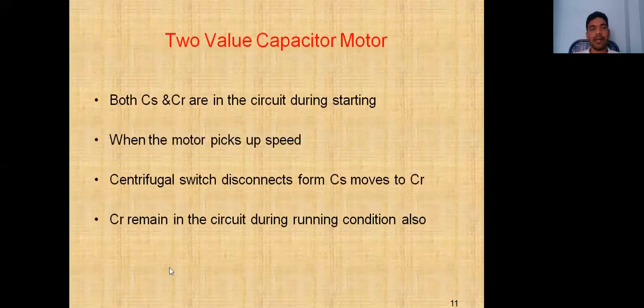Both the starting and running capacitors are in the circuit during starting. When the motor picks up speed, the centrifugal switch disconnects from the circuit and removes the starting capacitor.